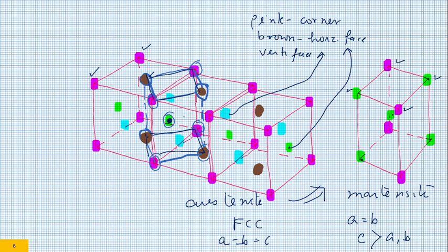Now, is it possible to predict, if you know the unit cell dimensions, what kind of compressive stress or tensile stress would be generated? Say for example, this is the volume of the unit cell. Upon transformation, it becomes larger. So if it becomes larger, or if it tries to become larger, what kind of stress would be induced? Would it be compressive stress or tensile stress? This is not a single unit cell. This is surrounded by other cells as well. They are not going to give way.